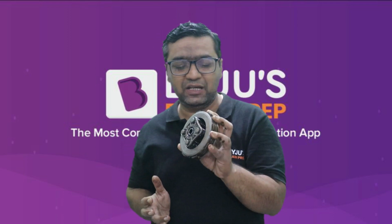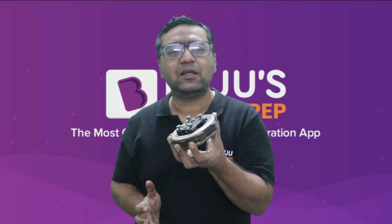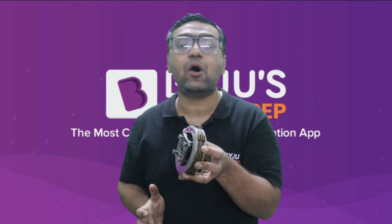So this is the basic working of friction clutches also. The only difference is that in a multi-plate clutch we have a larger number of plates, so that in a compact arrangement we can transmit the power and we can engage or disengage at the will of the operator. And don't worry, if you understand then it's fine. Otherwise I am going to tell all this now on the smart board with the animations as well.